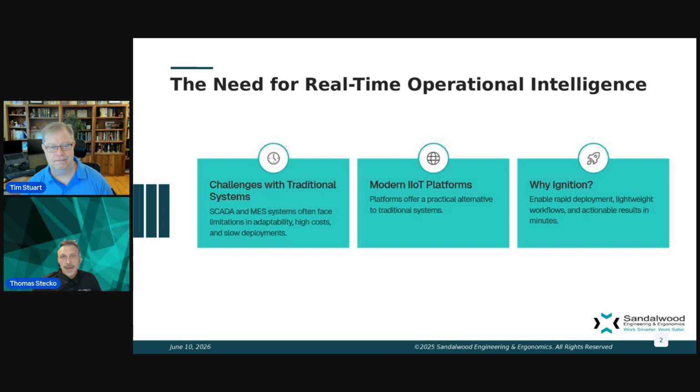I mentioned rigid, limited flexibility as a previous con. And as you mentioned, if I need to use an OPC UA server, or a third party application which connects my machine data through something and then into my SCADA application, that's an extra point of failure, or an extra layer that I need to maintain, troubleshoot, and validate my data in two separate systems.